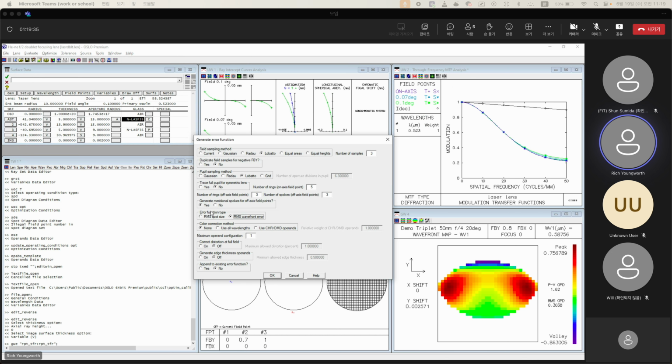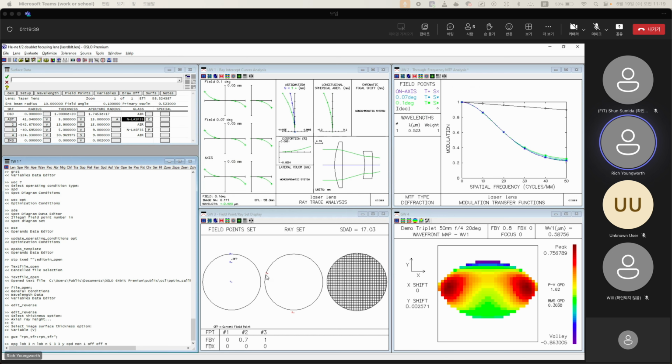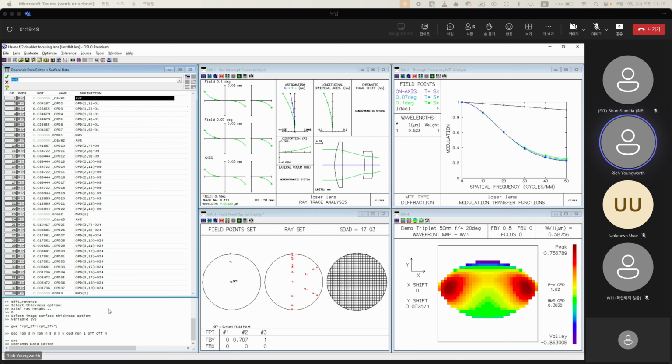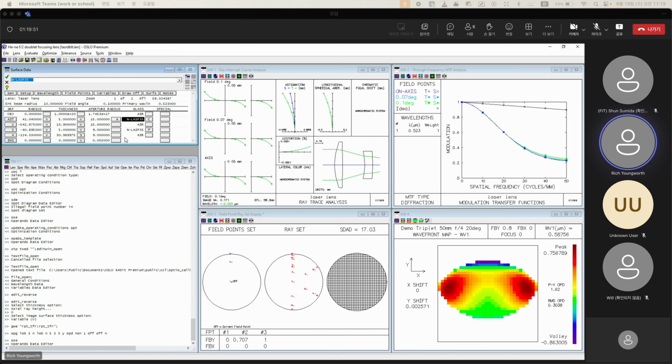And certainly review the different changes if you like. Now, if we hit OK, and then I come back here and let's just do a GRST, you can see we've got certain sampling. If I come here and look at our operand set, we've defined a bunch of operands and we have our variables. We have all the elements now to optimize. Why don't we just do it?